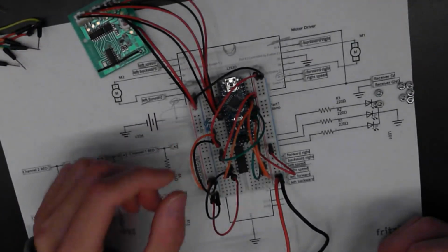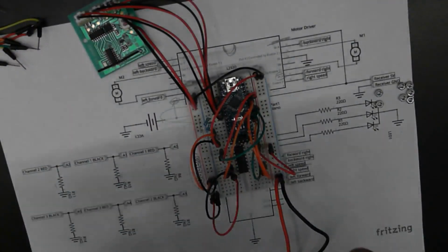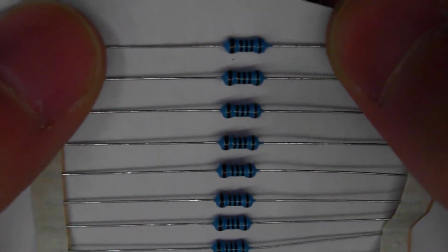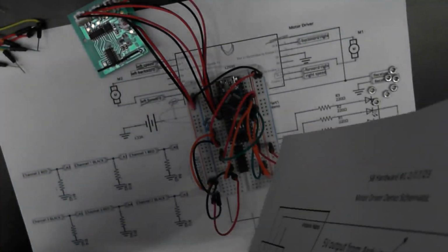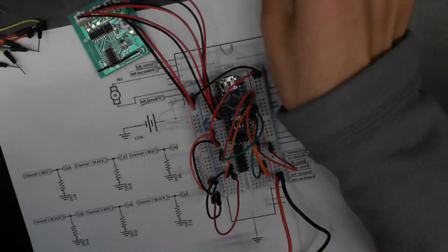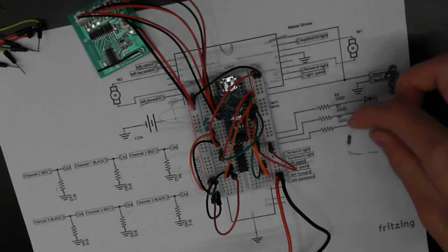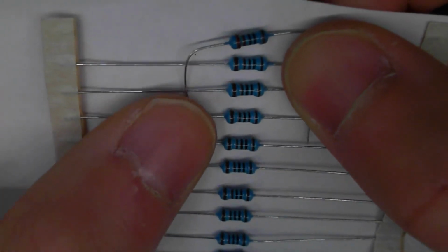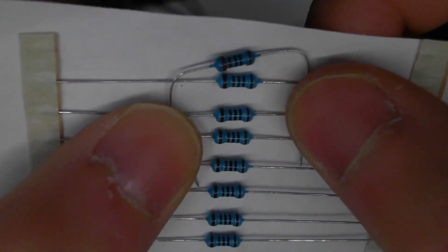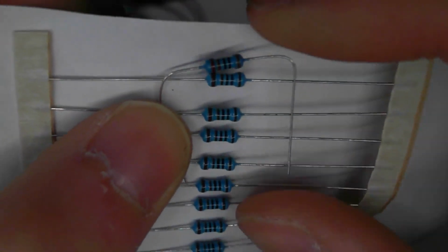So in your kits, there should be 6 1K resistors. It's a little bit hard to see, but they're the ones that are colored black and brown. As a reference, here are the 220 ohms that we use for the resistor. This one's a little bit clearer. It's really hard to see because red and brown is pretty close, but the one on the top is our 220 ohm. Those go to our LEDs, which is not what we need right now, so you can ignore those.